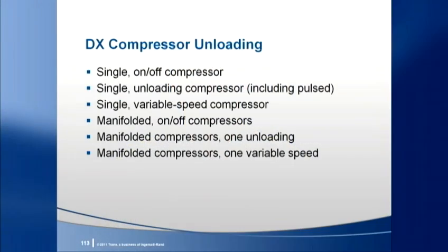The cooling load on a dedicated outdoor air unit varies from near zero capacity when the outdoor air conditions are close to set point to needing full capacity when at design conditions. The need to unload refrigeration capacity to reasonably match the load is important both for efficiency and maintaining acceptable space conditions. All of the compressor unloading technologies listed here have limitations.